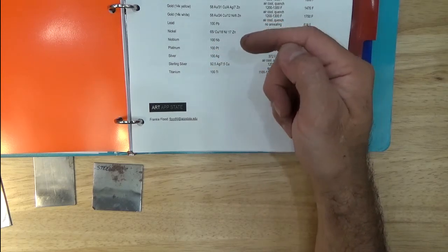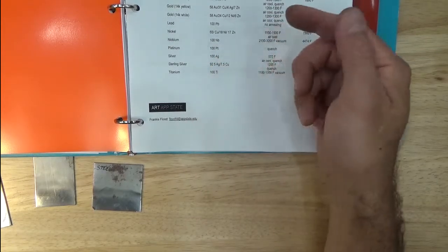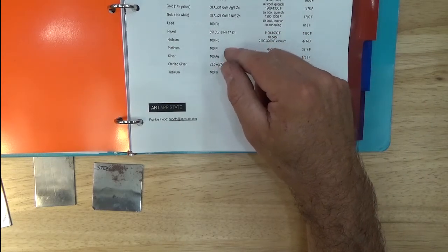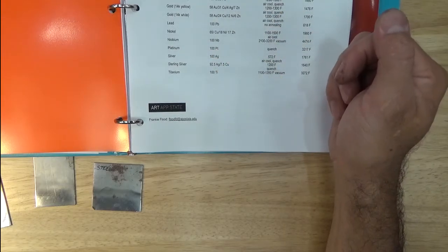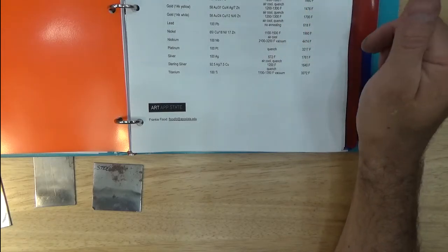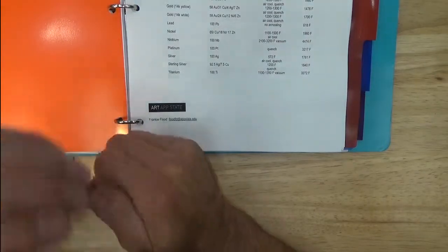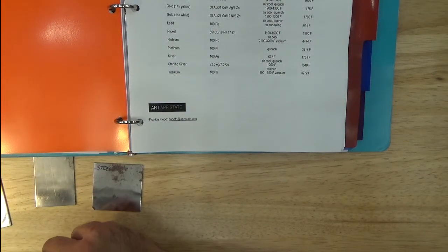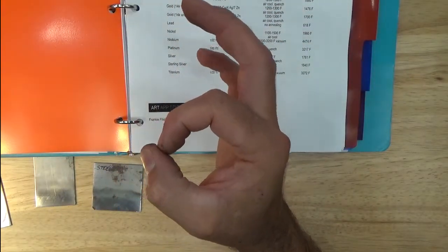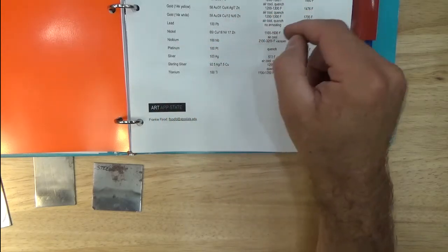And if somebody has reactions to sterling silver because of the copper content, fine silver might be a nice alternative, although it is fairly soft, so it deforms easily as a piece of jewelry. But we work with it in terms of making wire, like fine silver jump rings. It can be fused to itself, which is a neat attribute of it. We don't have to use silver solder in some instances where we're just bonding a ring or a jump ring or something like that in wire.